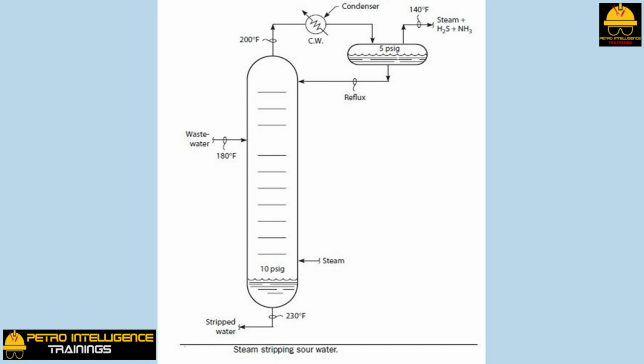2. A portion of the stripping steam is used to break the chemical bond between the water and the H2S and NH3 in the wastewater. When these gases first dissolved in the water, heat was evolved or released. This is called the heat of solution. When these same gases are driven out of the wastewater with the stripping steam, this same heat of solution has to be supplied. Again, this heat comes from condensing the stripping steam in the water flowing across the trays in